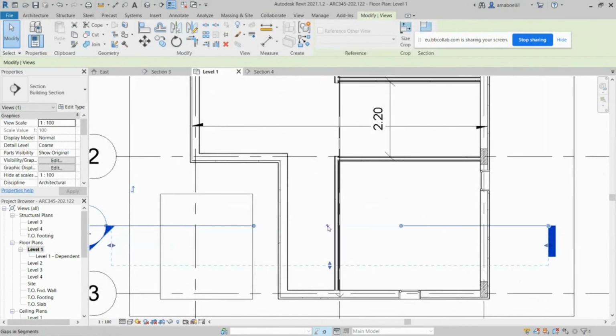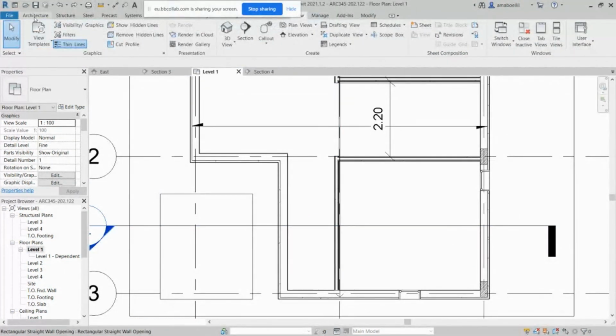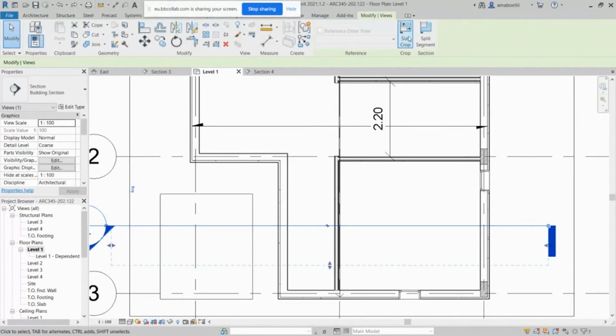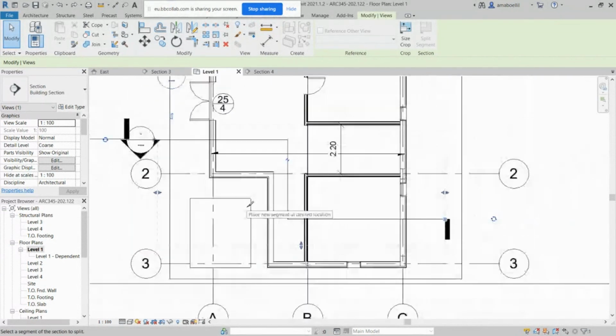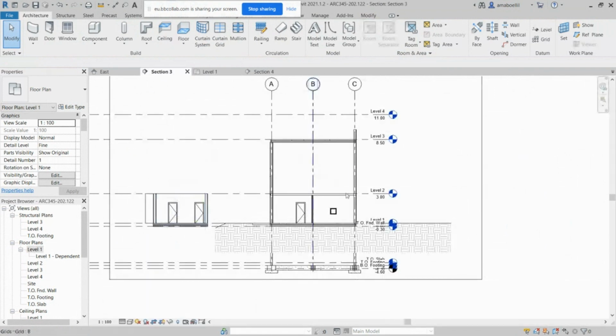Of course, you can develop elbows, as we talked about here. You can create an elbow, or you can cut in here. Let me see that. Pick this. You can crop for sure, and you can split. I don't want to show something that is outside my building, so I can split it from here and drag it to this portion, or drag this as I want to see it, so that this is a section that is just projecting two different lines for me. And I have to be careful with this, not to mess up what I want to show in my building. So this is how you can do it in detail, what we want to show in our section.